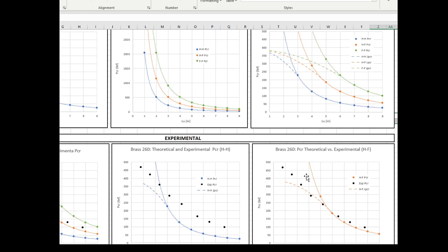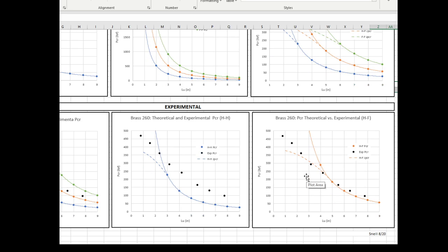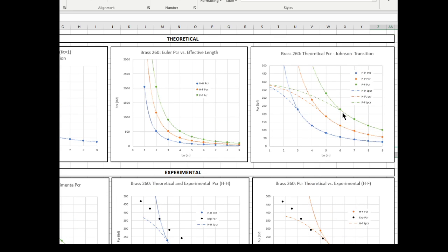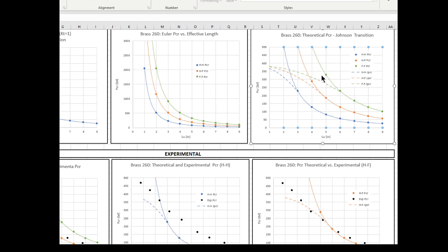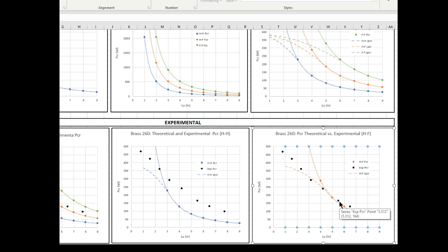But you may remember these graphs from the week 3 buckling assignment, and we were plotting Euler's critical buckling load equation and Johnson's to get the theoretical layout so that we could use this in this truss project. But also we were plotting our theory, and I'm not going to say more about that because all I'm talking about is the Truss Analyzer right now. But I did want to mention that, so for example, here's some data, the black dots, and we might then apply a linear trend line to this and put that equation into the Truss Analyzer.